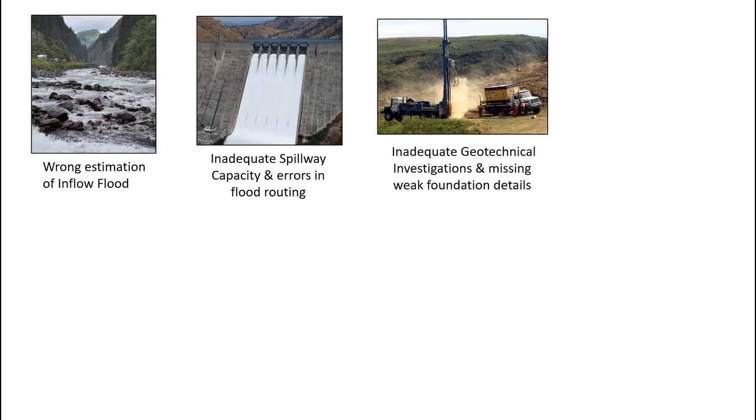If we miss shear zones or weak zones at this stage, after the dam construction, there will be problems like settlement of dam or sliding of dam. Weak zones identified during investigations should be carefully examined and have to be treated before the construction of the dam. Suitable remedial measures have to be taken.